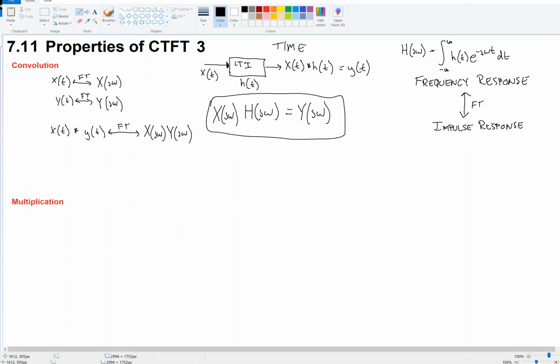This forms the second big result of signals and systems. Remember, the first big result was this, actually. And now the Fourier transform of that equation is this thing here. I want to point out, again, we have the multiplication of the input spectrum, the input frequencies, by this frequency response of the system to get the output.